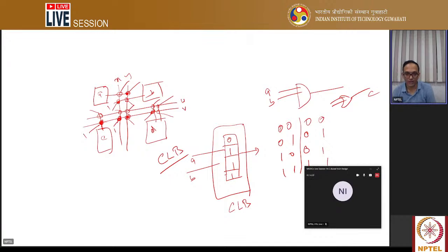So there is no AND gate, OR gate, or XOR gate in the FPGA board. They have this kind of CLB, which is nothing but a memory. Based on your design or the size, you identify the input output behavior and you store the value there, right? Then the same thing can be implemented for any gate.